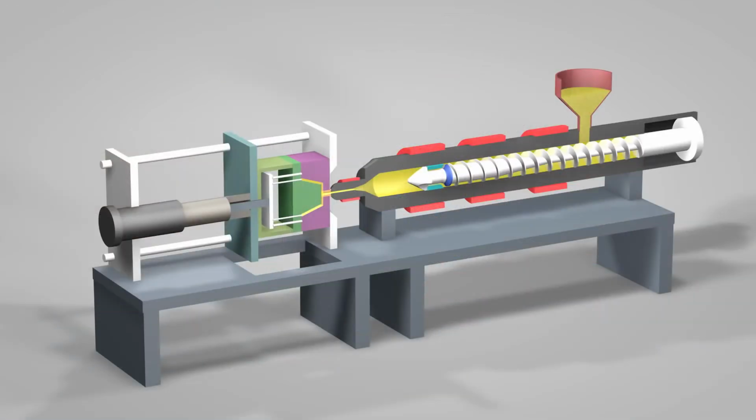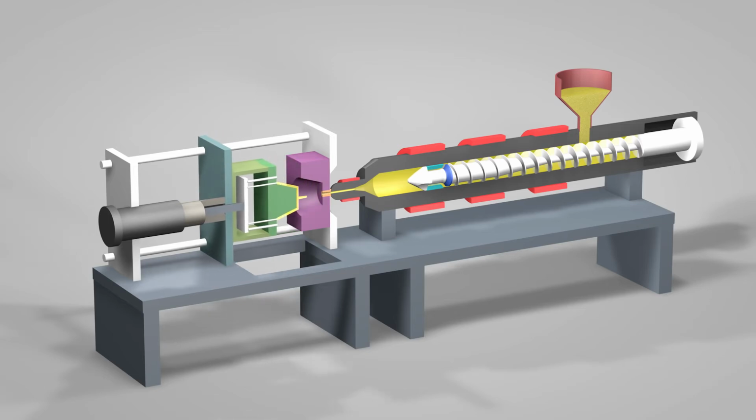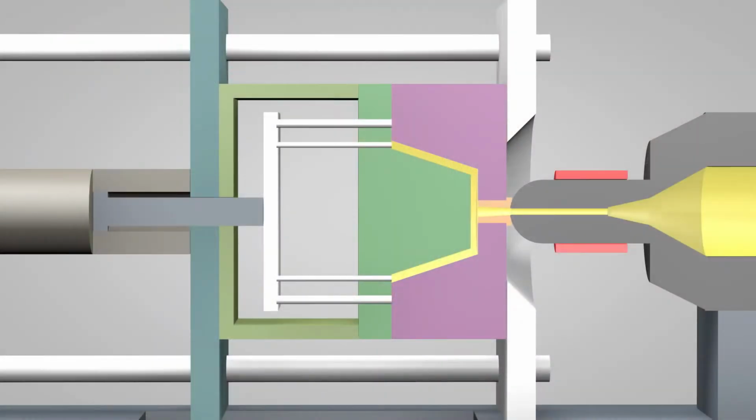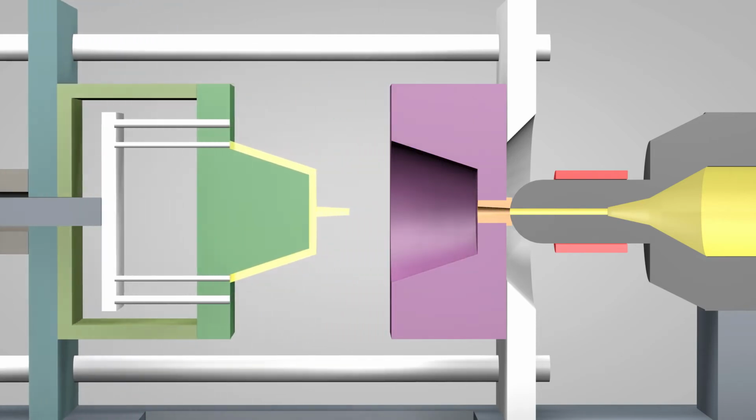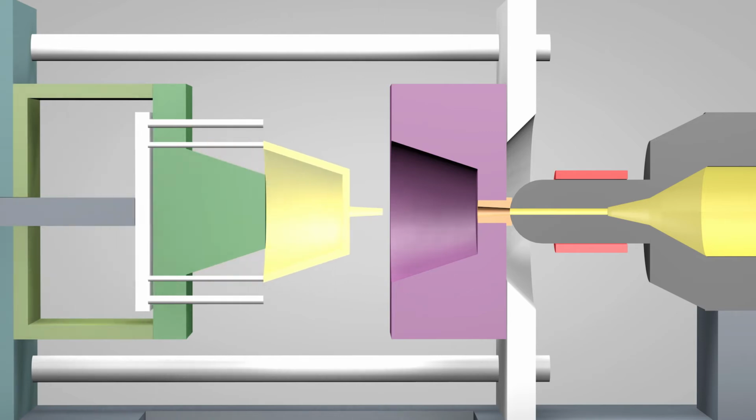After the injected part solidifies, the mold opens. As the mold opens, the volume increases without introducing air, which creates tremendous suction that holds the mold together. So at first, the mold slowly opens several millimeters to allow air to rush in and break the vacuum, and then the mold quickly opens the rest of the way so the part can be removed. These precision machined steel molds can cost hundreds of thousands of dollars. Removing the part from the mold can be difficult.